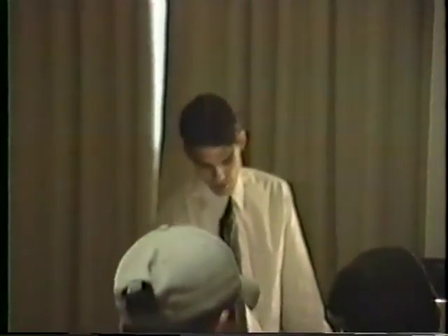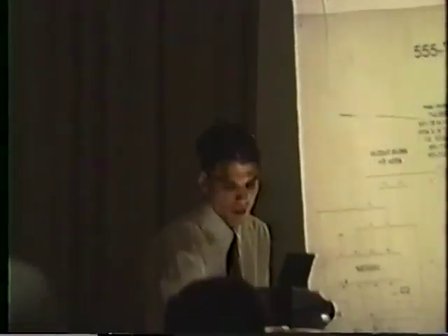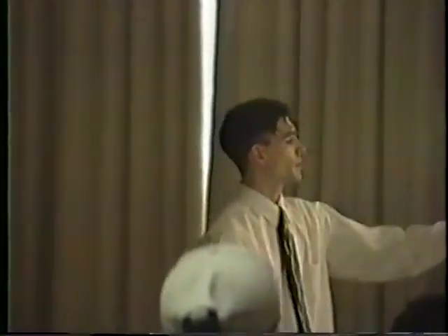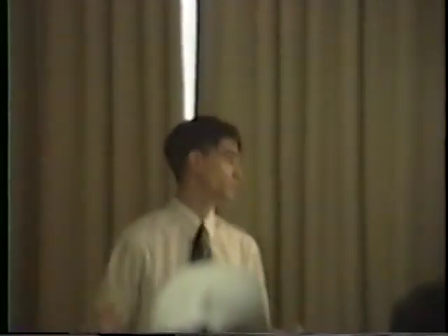And we had to determine the on time in order to get the correct decibel levels for this particular system. Here's our timing circuit, and what we did is we used a 555 timer to determine the time. This is an astable, which means it has 2 states, 0 volts for low and 5 volts for high, and neither one of them is stable; it constantly pulses.